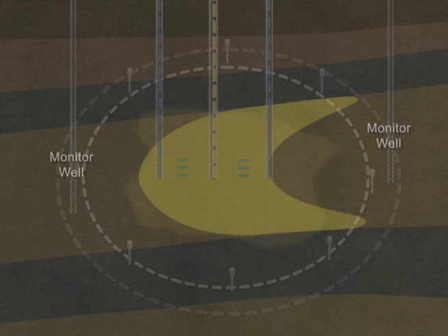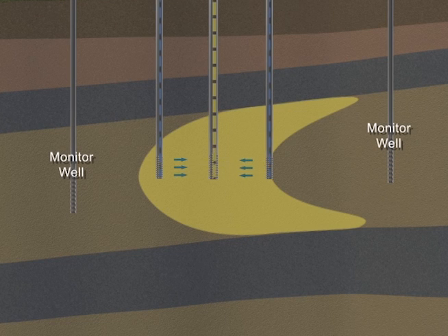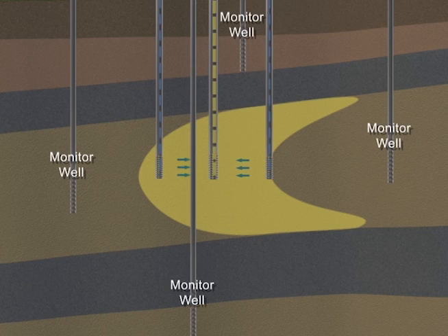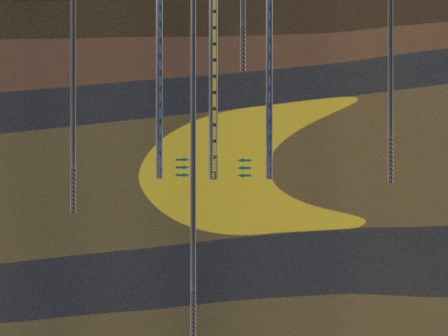Monitor wells are also placed within the well-filled area in the overlying and underlying aquifers to monitor groundwater quality. To contain the lixiviant and affected mine fluids within the aquifer exemption boundary, the well field is slightly overpumped, i.e., more water is pumped out than is injected, resulting in a natural inward flow toward the recovery wells and containment of the groundwater to the immediate vicinity of the well field. This overpumpage is called bleed.